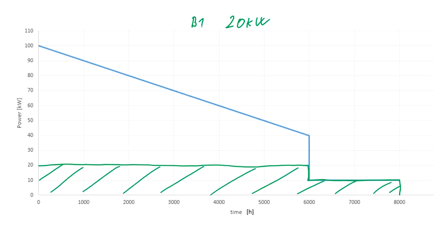and then we have the remaining 80 kilowatts, which could be covered by the second boiler, where for a very short period of the year it will be running at the full power, and then the power output would be decreasing as the heat load is decreasing all the way to 20 kilowatts over here.